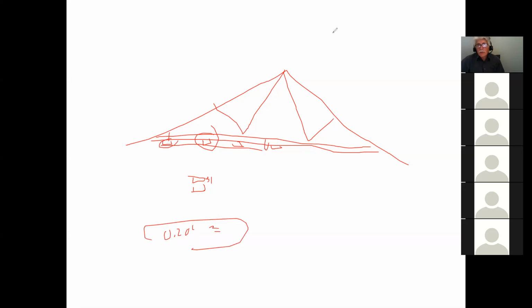All I'm saying is that these are things I've never worried about. The 15-pound tar paper, I shouldn't even have put it in, but I want you to understand that a good roof usually has a 15-pound paper underneath the asphalt shingle. Some people put the asphalt shingles directly on the plywood.